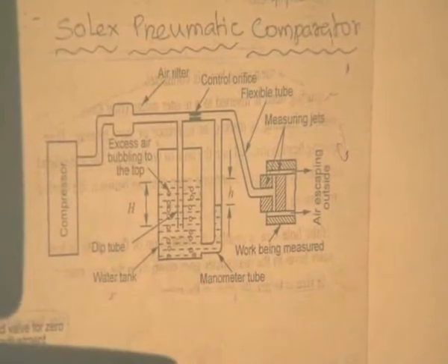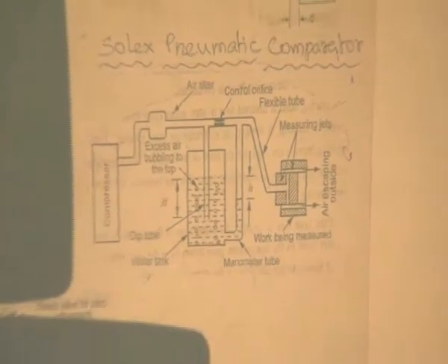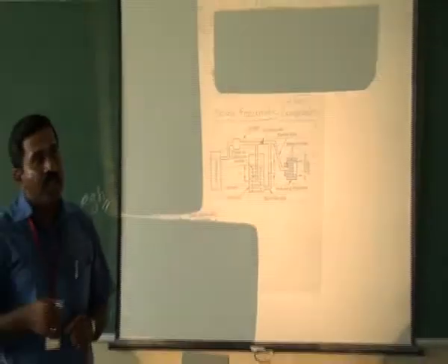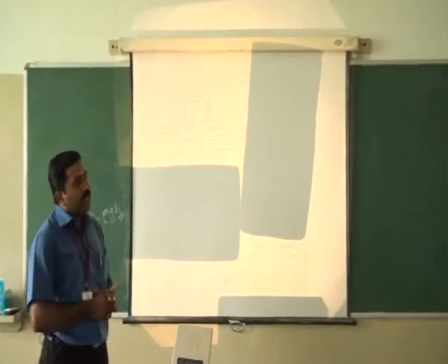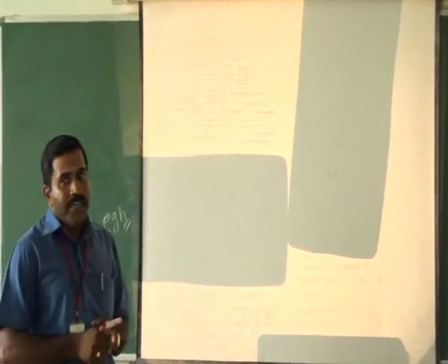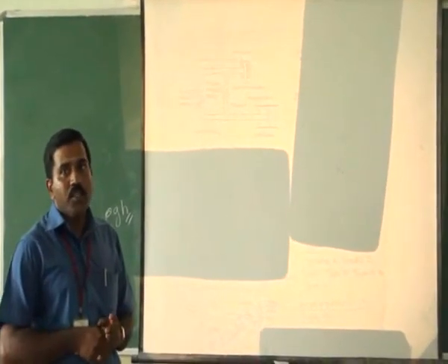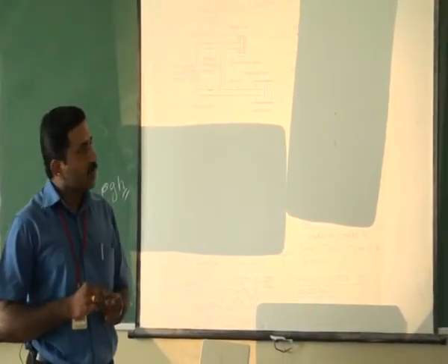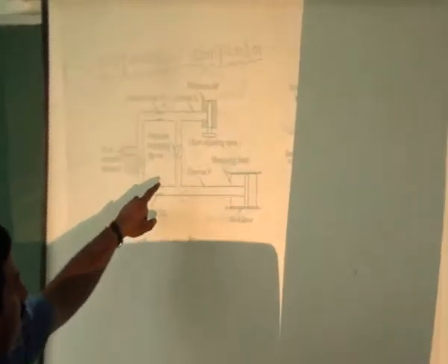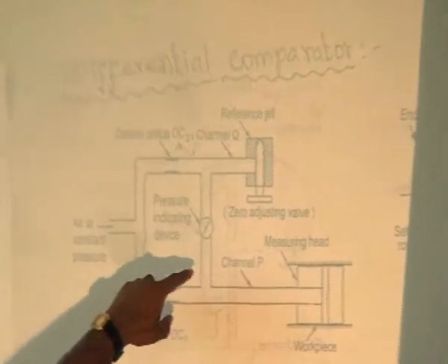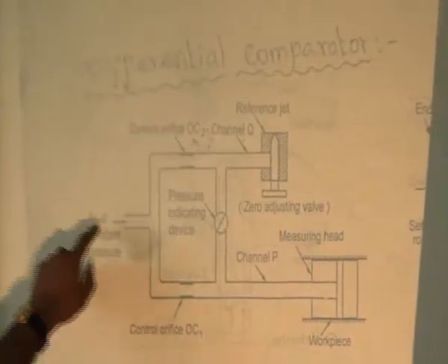So that is a main thing. Another type of pneumatic comparator is the differential pneumatic comparator. We already discussed the Solex pneumatic comparator, and the next one is the differential comparator. The differential comparator also works based on back pressure.